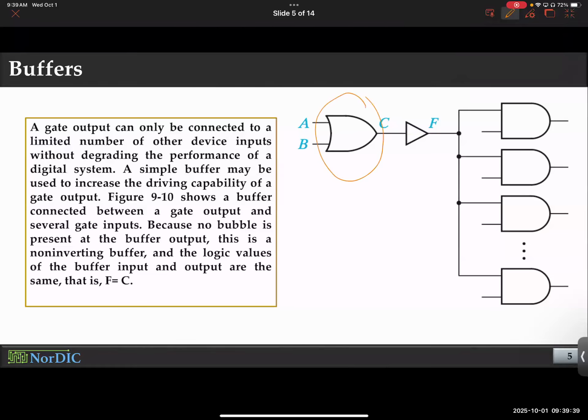Remember, without doing anything to this logic gate, what you can do is you can use a buffer. The good thing about a buffer is that it doesn't change the logic, but it can be sized up or down. Remember, the larger the size of a logic gate is, the more current it provides. So imagine you design an OR gate and use it everywhere. You don't change the size of every OR gate. You use it exactly as is, but you have different sizes of buffer.